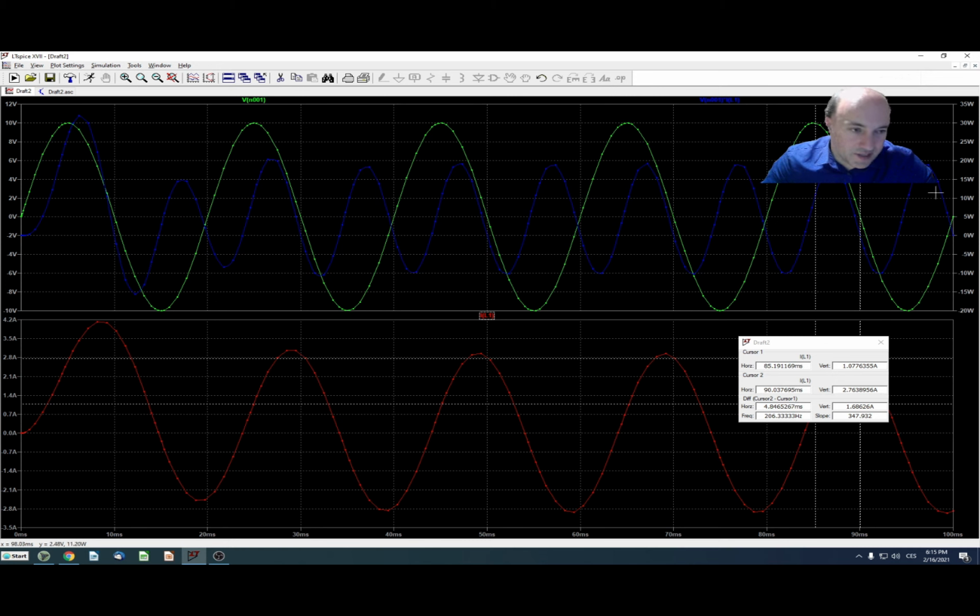And this is exactly what we see here in our result. Here we have about 20 watts of power, but here we have about minus 10 watts. So it means that the power is being delivered from my circuit back to the power supply. It's traveling back and forth between the power supply and the load.